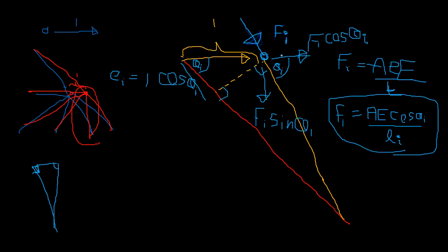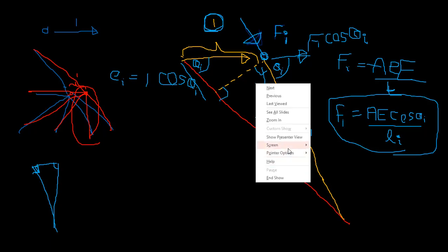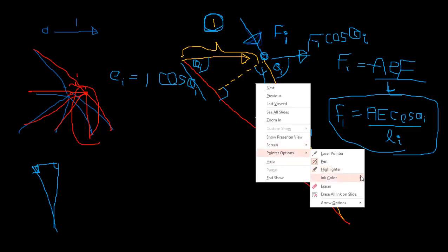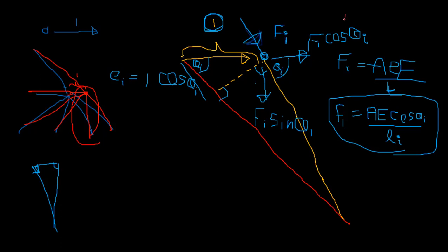So you apply a unit force, sorry, unit displacement. Okay. Sorry if I told you unit force. This is not a unit force. This is a unit displacement because we are in the displacement method. And we check what will be the force applied at the joint, right? So the joint force will be F cos theta I and F sin theta I, in the direction we took the sign convention. This is positive in the first direction and this is positive in the second direction, right?